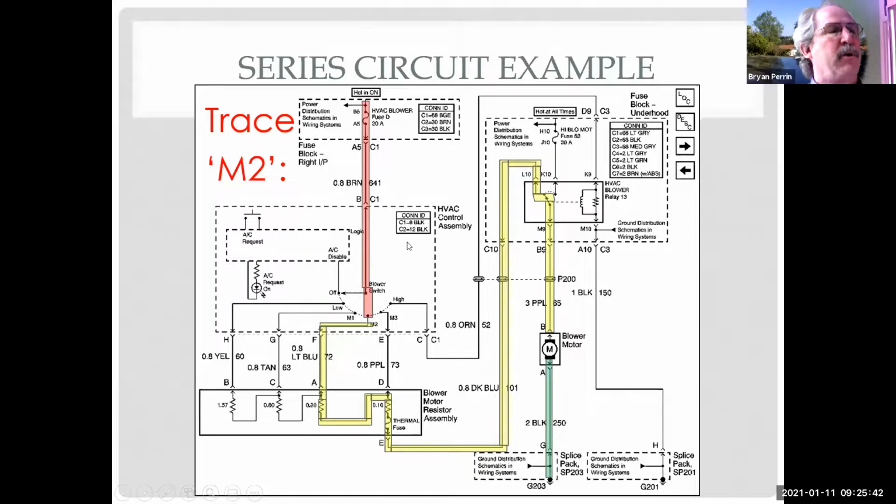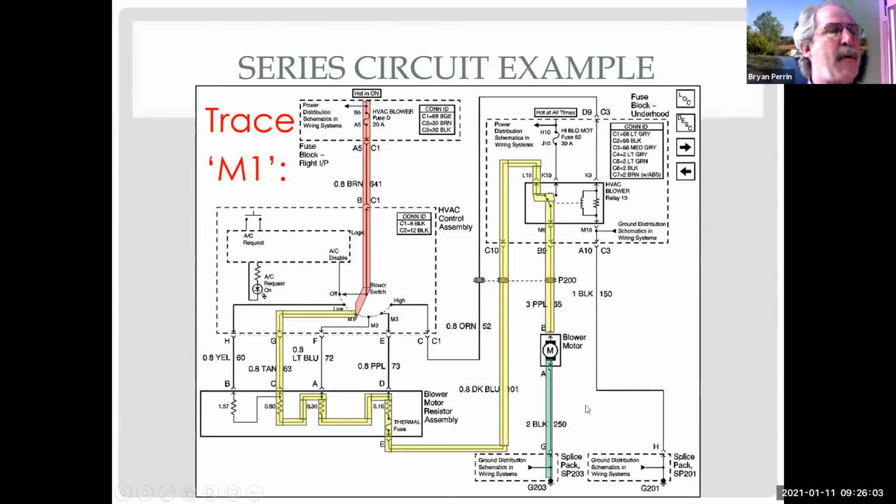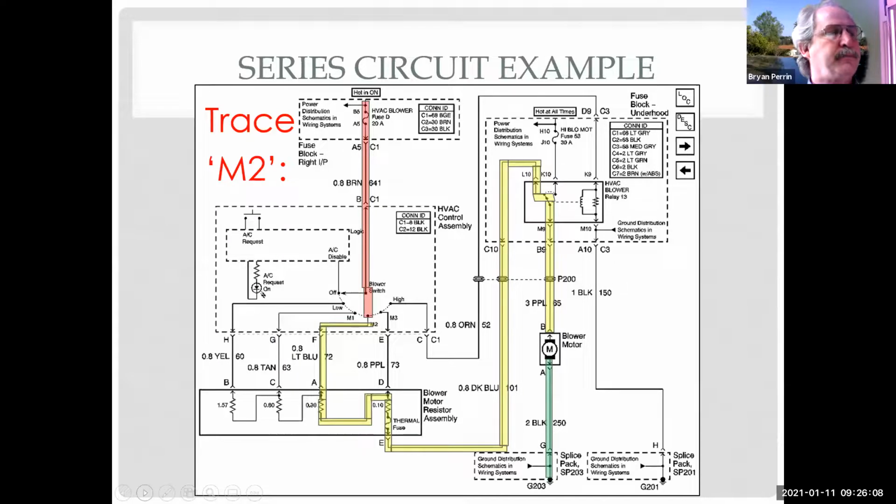So this is a computer. So wait a minute, here's this complicated computer and it controls the blower motor. But when we get down to it, this is a pretty simple series circuit we're using, isn't it? Each of these is its own little series circuit. Nothing intimidating about that. And since I have several of them, I can compare them to each other and figure out what is working and what isn't working to figure out where the problem most likely is in the system.